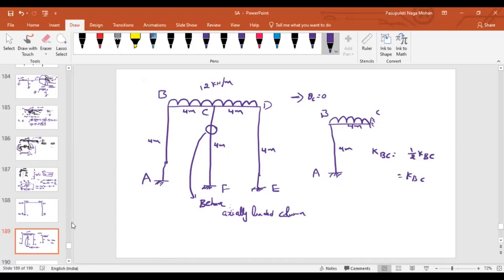Now, can I know where the problem is? Sir, there is no support, sir. How can we find, sir? These are continuous members, isn't it? We are discussing whether there are fixed joints or they are continuous. Whenever you are talking about continuous joints, the moments will be transferred there. As you can see here, everything is a continuous joint, so moments will be distributed there itself, everywhere. There is no pin support, nothing like that. Everywhere you have to consider it as a continuous support, which means at every support, moments will be distributed.